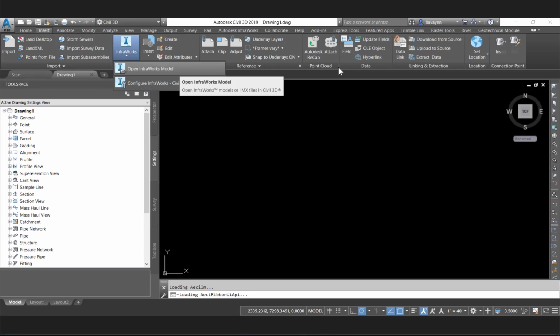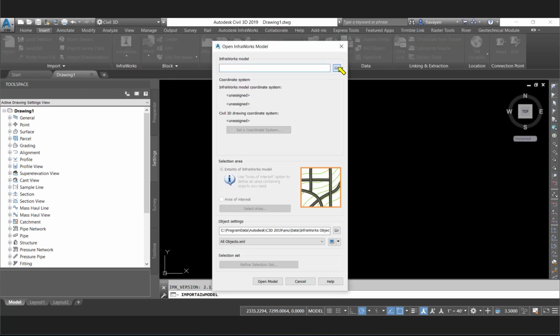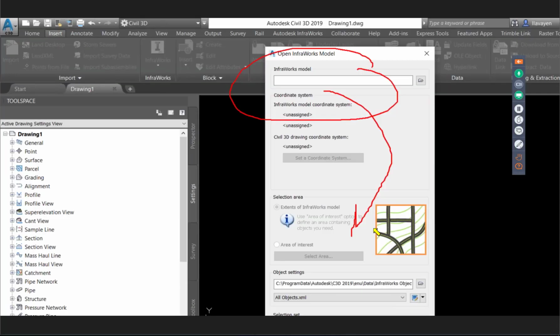And once I pull that Jacksonville model, I have the option to really focus on an area, not to bring every existing condition, not to bring every existing centerline roadway or my proposed centerlines or my pads, but to focus on an area and bring it in. Otherwise, you're going to be sitting here spinning your wheels for quite a while if you're trying to bring in that max limit of 200 square kilometers, or you're dealing with 100. Even if you're dealing with a small city block, maybe that's going to be easy enough to bring in.